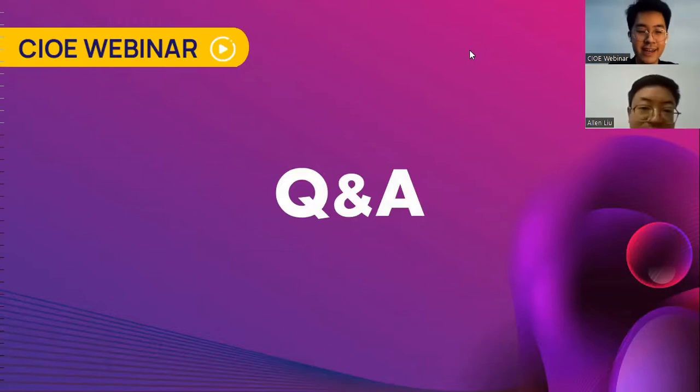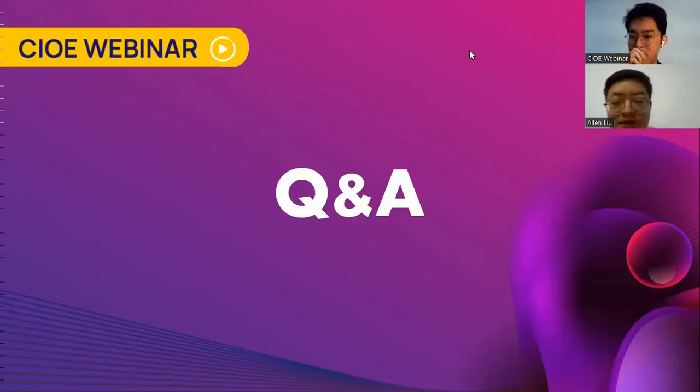Okay, sure. And the next question will be: you mentioned the thickness of the gold tin is around 6 micrometers, I don't know if I was correct, so why don't you use thinner gold tin materials? Yes. Our standard thickness of gold tin is 6 micron, plus or minus 1 micron.